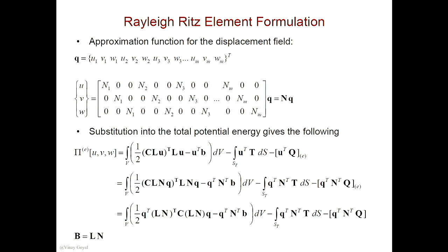So what does it mean that u is the sum of all the individual u's of each node, as opposed to an average? We're not doing an average. We're interpolating the displacements inside that cube or hexahedral, right? We're interpolating that displacement using the nodal values and the interpolation functions that go along with them. So that's basically our approximation function, similar to heat transfer problems, where in our case we had a rectangle.